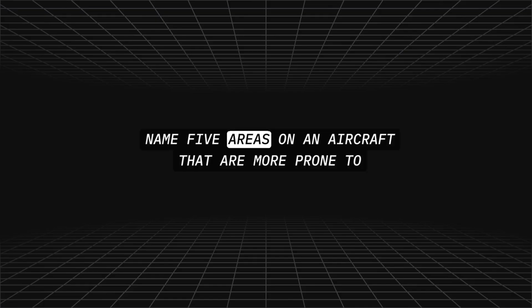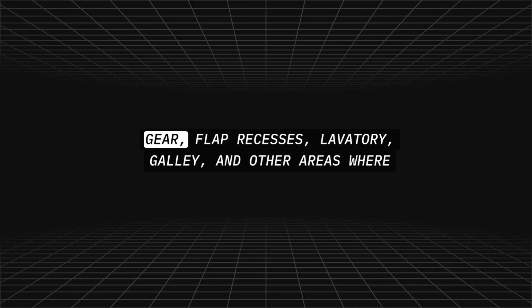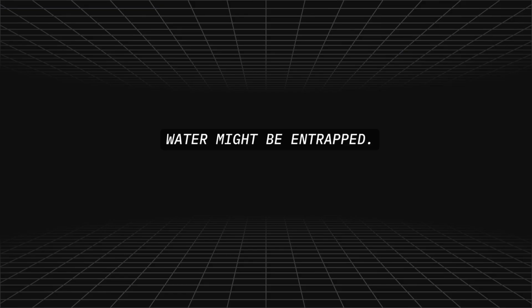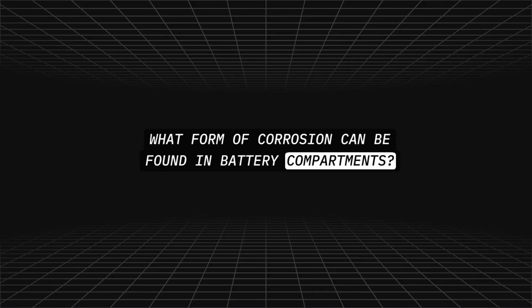Name 5 areas on an aircraft that are more prone to corrosion. Battery compartments, bilge areas, wheel wells and landing gear, flap recesses, lavatory, galley, and other areas where water might be entrapped. What form of corrosion can be found in battery compartments? Direct chemical corrosion.